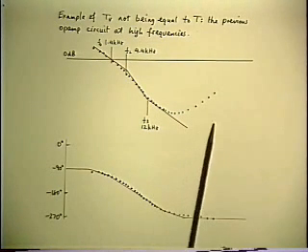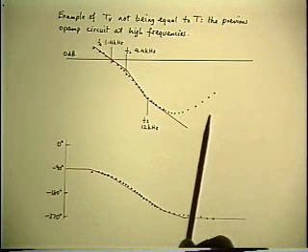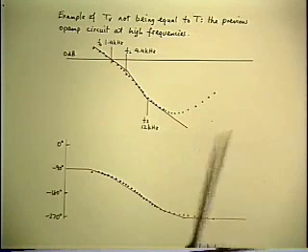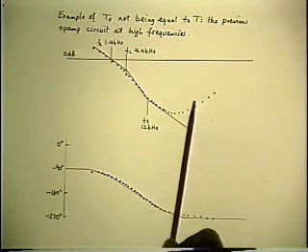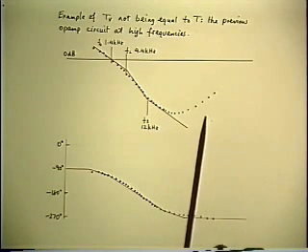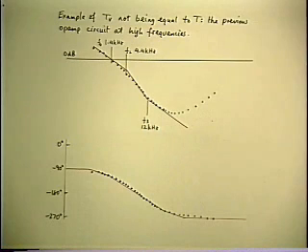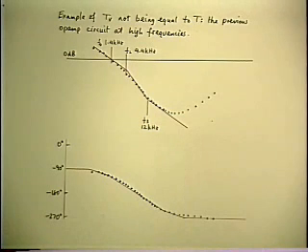And the most likely reason for that is that the measurement we've made by injection of a voltage at a point in the loop, it's turning out maybe that it isn't an ideal point. And maybe we're not satisfying those impedance inequalities, which means we are not really measuring the true loop gain, we're measuring something else. So that's the thing we need to go back and check up.